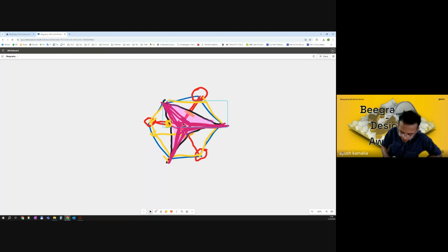So our parameter of opening and closing is now reduced to 1, where I want to place this particular point on this line. If it is very close to the center point of the hexagon, I am in a fully closed situation in the facade. If the point moves far back towards the edge of the hexagon, it is almost in a fully open situation. Now we just have to make it parametric.